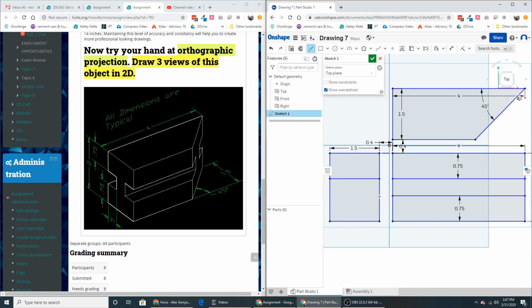I'm going to grab the line tool again, hover, stretch out, see that little yellow line, click, and click. And this time I won't press enter because I'm not going to try to type a dimension. I'm just going to press escape. Okay, I've got these lines in. Now I need some vertical lines representing this and this. And they are 0.5 in from the edge.